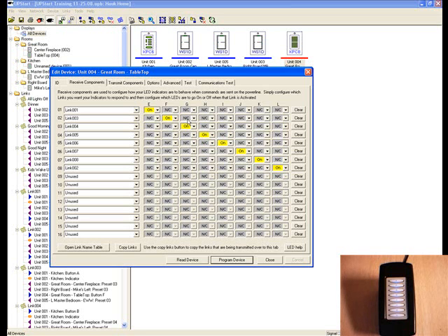The good part is I can run independent scenes. Go to my G button. So I can run different lights in the system. Now, in this case, my I scene was the last scene that went out. If I want to reactivate my E scene and I push that button again, that turns off the LED light. That now deactivated the E scene. So to activate it, I must press it a second time, and that will reactivate the scene.